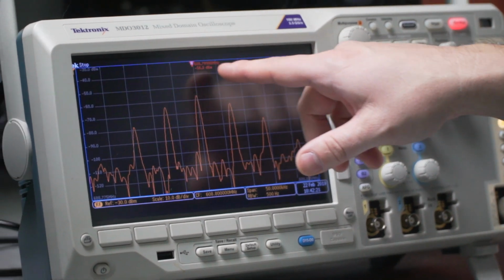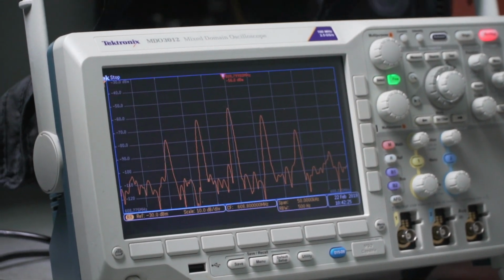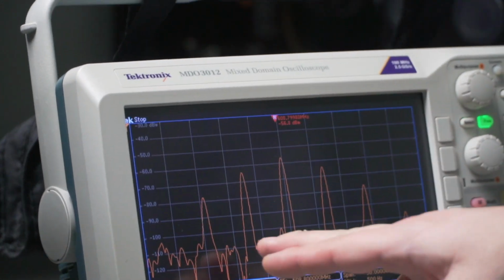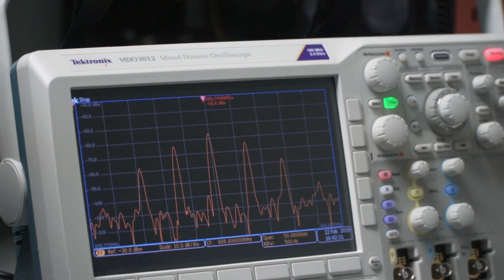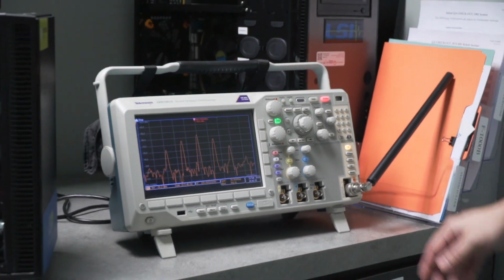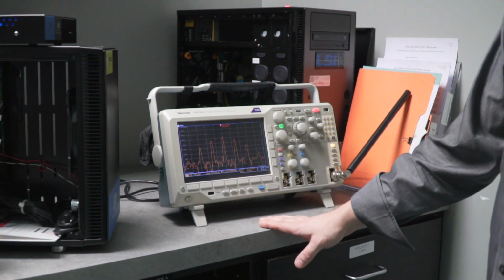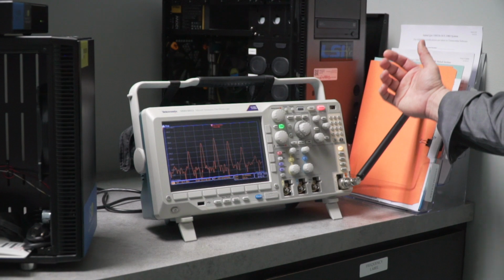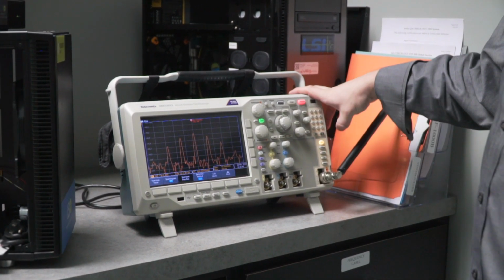It's transmitting at 608.7998. That's the accuracy of our transmission. You can see a nice carrier with the sideband. So that's the data that we're actually sending to our receiver, and everything looks good. Signal strength is -56 dBm, which is fine considering we've cut all the antennas off. Cool.